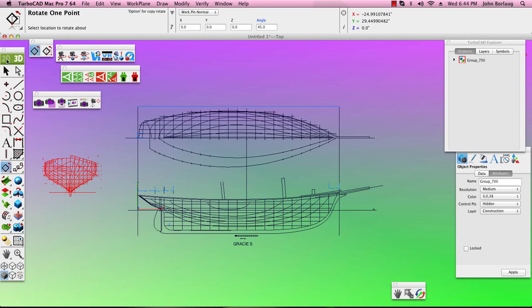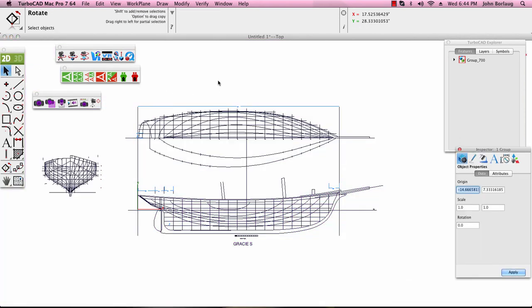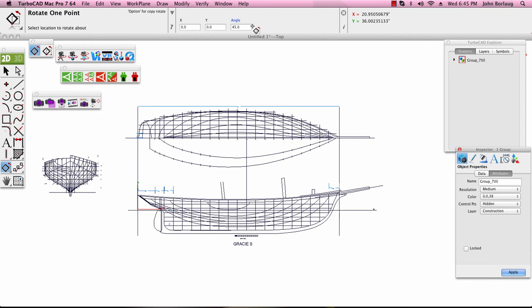Now one of the other things happening too is if we're in 2D. What I've just done here is changed out from being in 3D to the 2D. So let's start right here with our 2D. And we see data, and this is our data points center for our group. So let's do a rotate, and we see that there's only 2 types of rotation because we're only looking at the one view. So we can rotate 3 points, which we won't do right now, or we'll do a single.